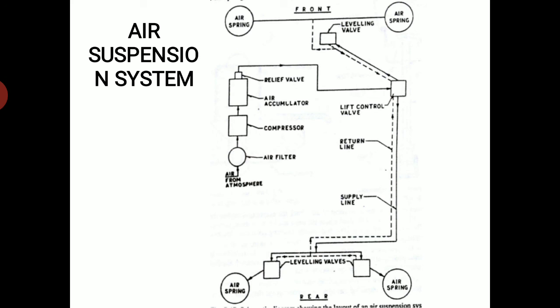The air suspension system possesses the following advantages over conventional metal springs. So what are the advantages of air spring over metal springs? The spring rate varies much less between laden and unladen condition, which decreases dynamic loading. Changes in headlamp alignment due to changes in the load are avoided. It improves riding comfort for the passengers. Longer service life for the vehicle due to improved smoothness of the run.